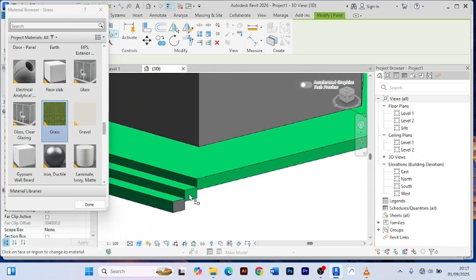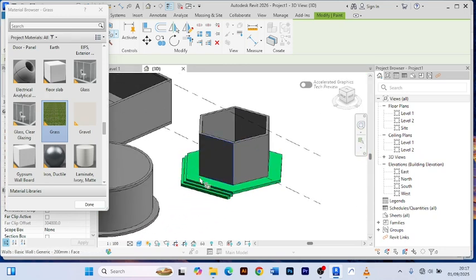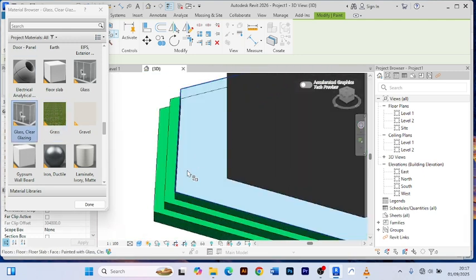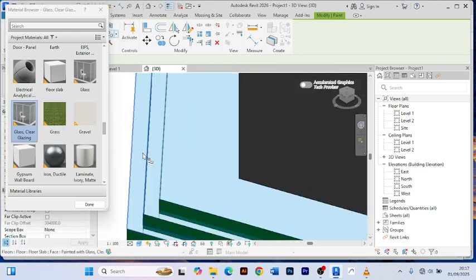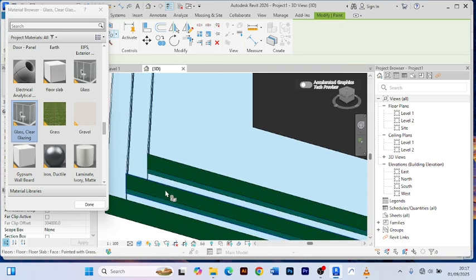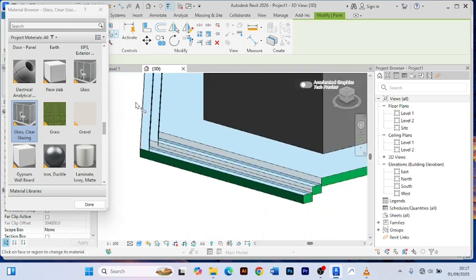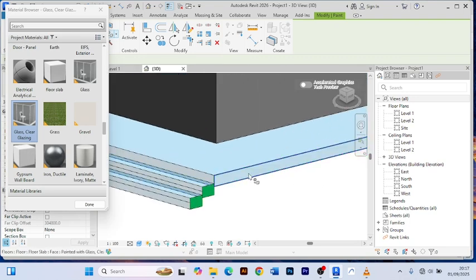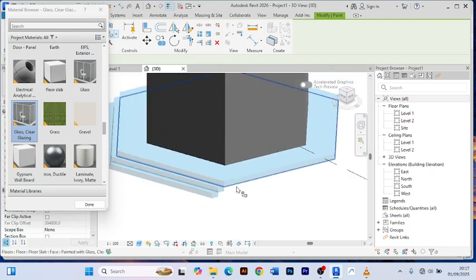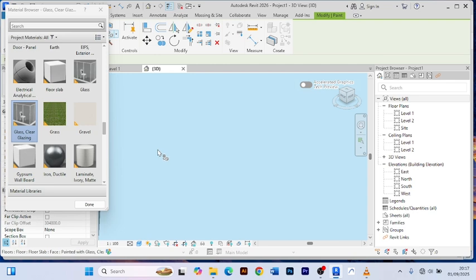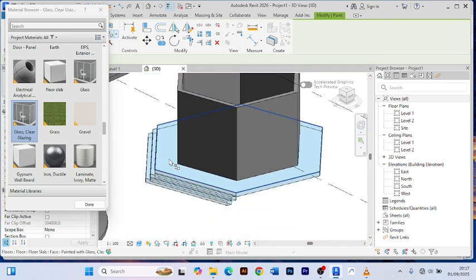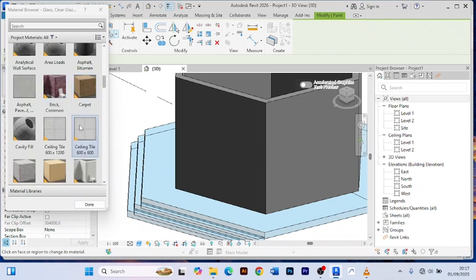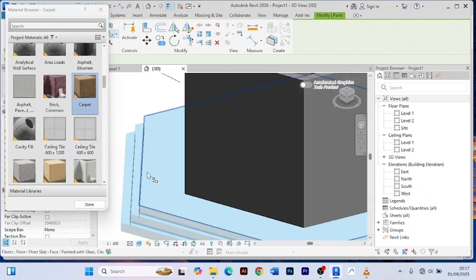So this is how easy you can do this. You can change the color, you can change it to glass. It looks like glass. So it's basically about just picking the line and picking the paint, and then you just place. See, now it is shining like a glass. It is actually looking transparent. So yeah, that is how you can change the colors.